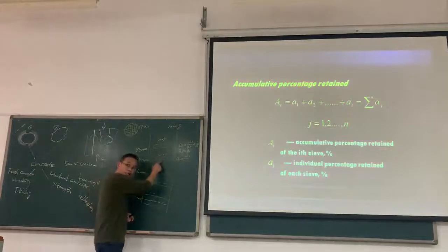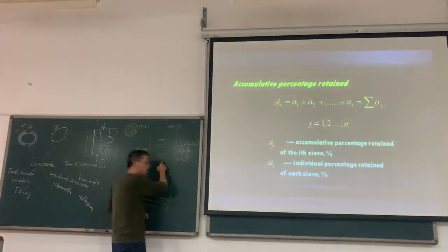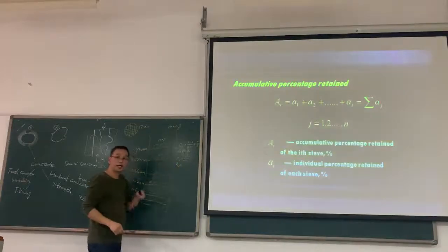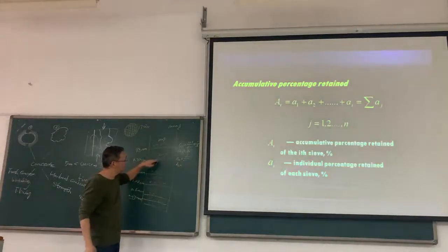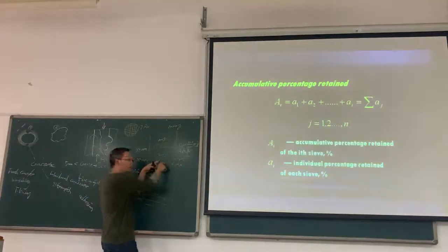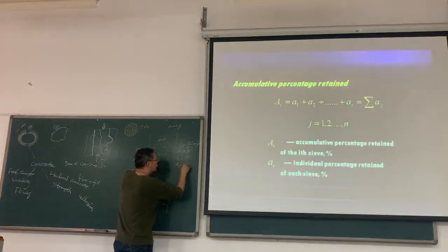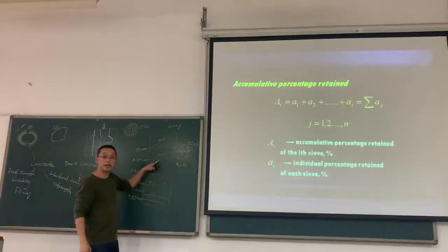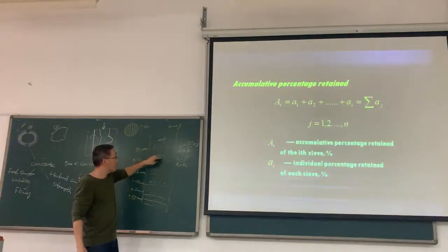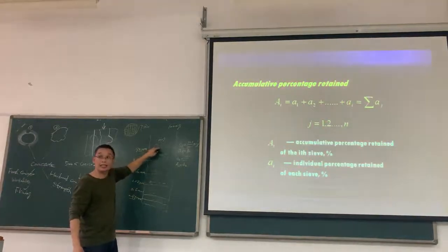But for this one, the accumulative percentage retained is the individual percentage retained at this size and above this size.